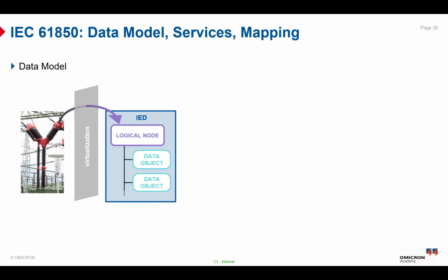And let me explain the difference between each of them, just to give you a clear overview of the terms. The logical device, represented as LD, can represent a functional unit of an IED, or intelligent electronic device. So it can be the protection relay. The main function of this logical device is to group multiple logical nodes into one functional unit. As an example, the logical device can represent a distance protection function or the overcurrent protection function.